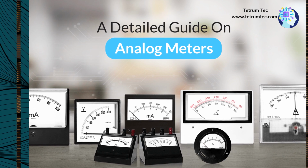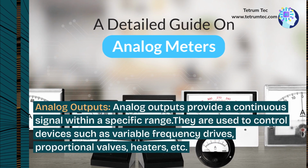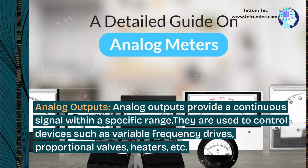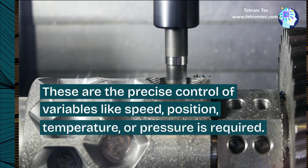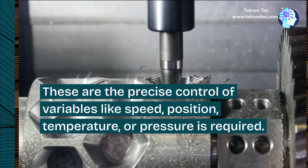Analog outputs. Analog outputs provide a continuous signal within a specific range. They are used to control devices such as variable frequency drives, proportional valves, heaters, etc. These are used where precise control of variables like speed, position, temperature, or pressure is required.